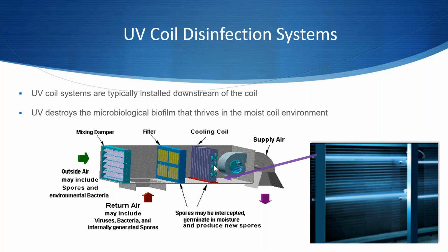If airstream disinfection is the only goal and they don't have enough space here, then the next best place is wherever we can get enough space to install the system for ease of maintenance and with the least likelihood of a lot of degradation of components. If there's a lot of plastics and components in a single cabinet of an air handler that you might have to either tape off or provide UV resistant wrap for, that's maybe not the best location. Although we can provide assistance in helping deal with those situations, that's probably not ideal.